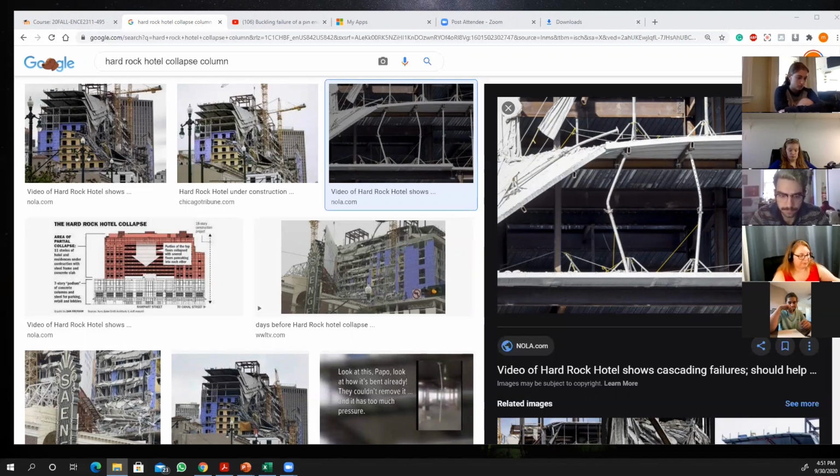conference room. These loads are based on statistical calculations. They know on average how much load can be applied on a particular section, and they use an equation that I cannot think of off the top of my head, but they input parameters such as the maximum occupancy. For example, if you're designing a theater, you look at the maximum occupancy, how many people you can fit in this theater. If you're designing a library, then you have the dead loads from the books.